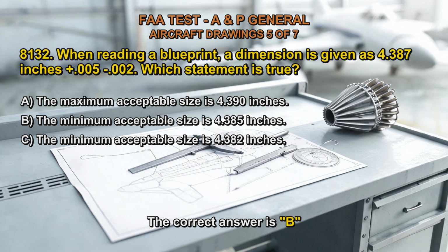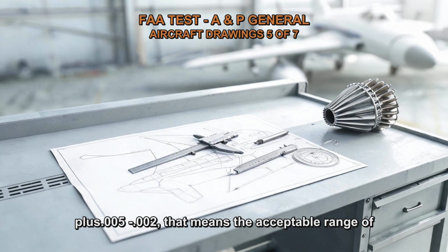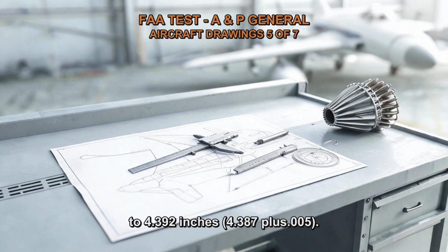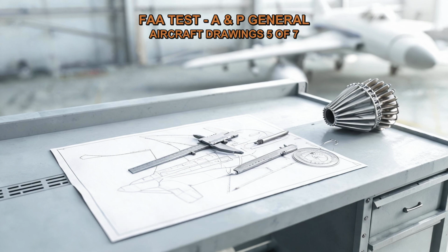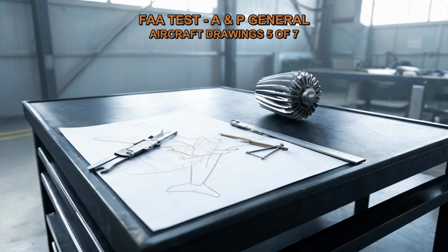The correct answer is B. When a dimension is given as 4.387 inches plus 0.005 minus 0.002, that means the acceptable range of the dimension is from 4.385 inches, 4.387 minus 0.002, to 4.392 inches, 4.387 plus 0.005. Any size within this range would be acceptable, but any size smaller than 4.385 inches or larger than 4.392 inches would be considered out of tolerance. Therefore, the minimum acceptable size would be 4.385 inches.